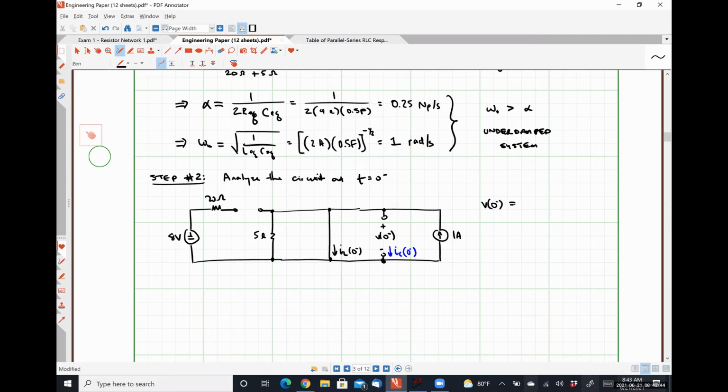So, what do you think the voltage drop should be? 0 volts. You're correct, but could you explain yourself? Well, there's no voltage drop across the resistor because all of the current would be flowing through the short circuit where the inductor is. Absolutely right.